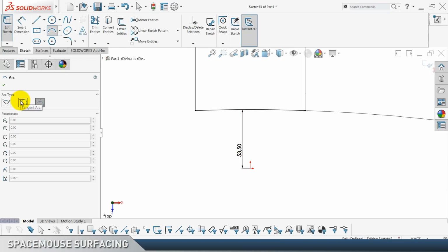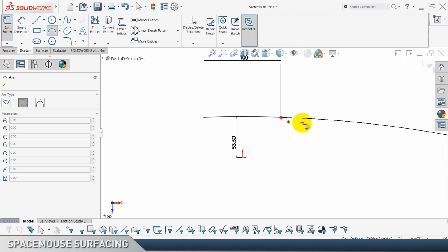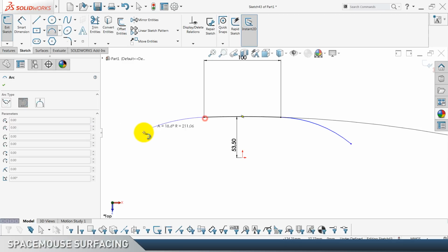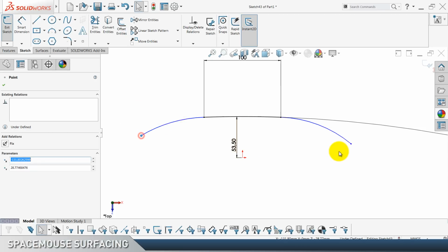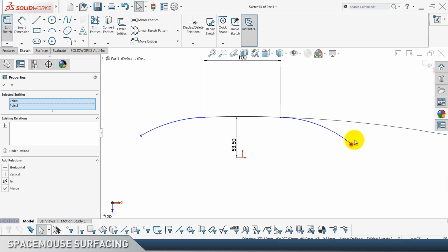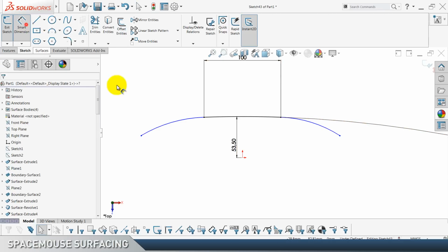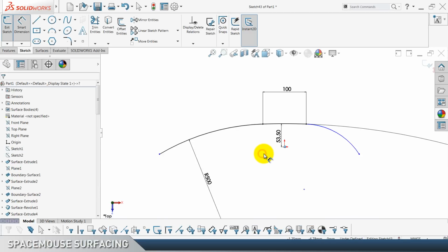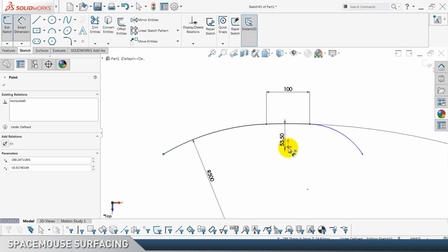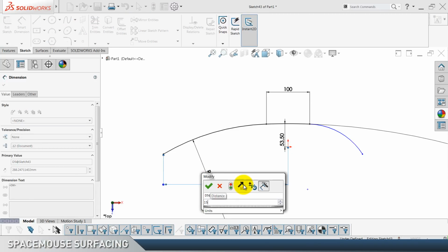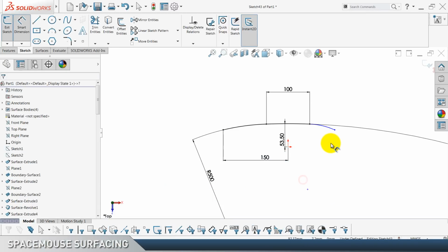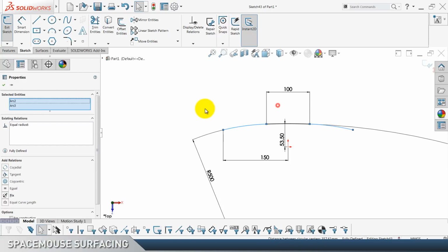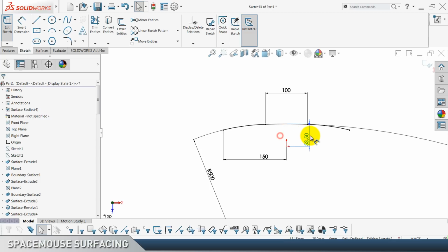And we just need another 2-point arcs. Actually, this is gonna be tangent arc. So going from this one like this, and from left here. Let's also make these two horizontal. Let's make this one 500 radius, and from origin it can go like 150, for example. Make sure that this one and this one, they should be equal. So that's pretty much it.